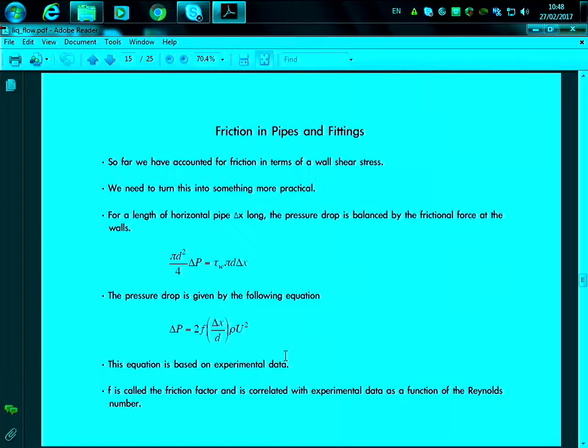So that's the same friction factor chart. Here it's very complex because it's very detailed, but this will be a summary. This chart, especially for the turbulent regions, comes from the Colebrook equation. So if you didn't want to use this chart and you wanted to input everything in a mathematical software, you would input that equation and solve it for the friction factor.